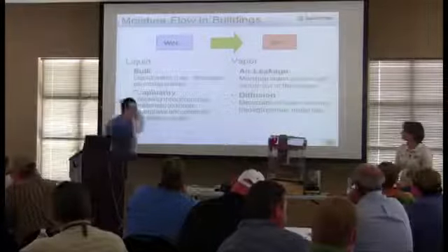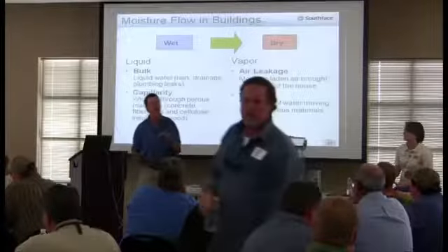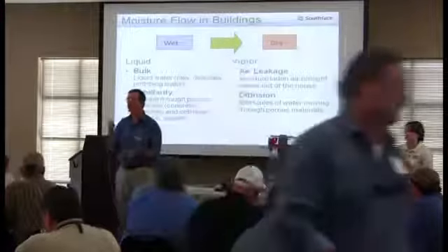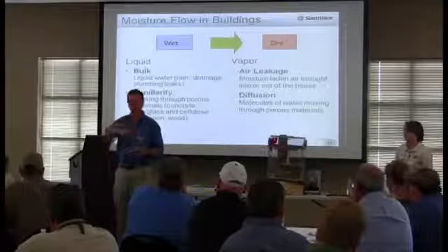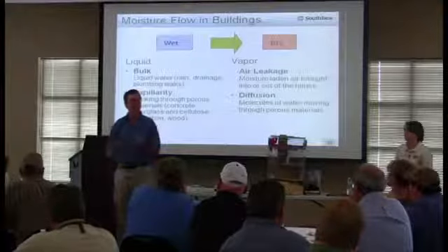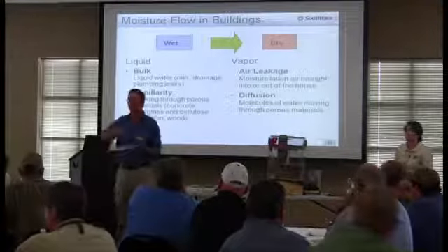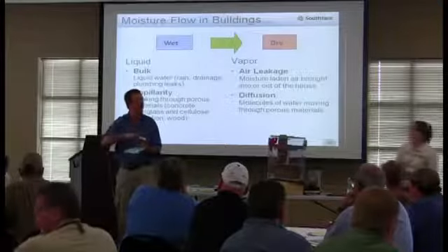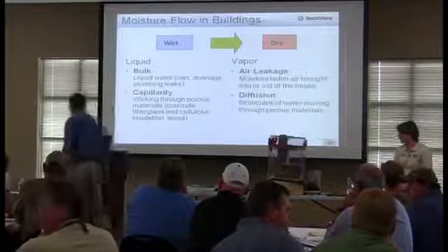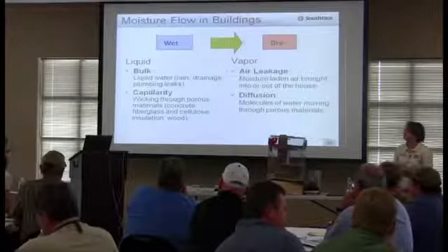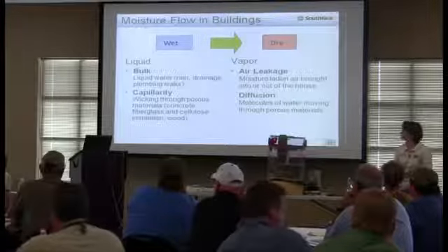And products like this seal gasket, when you have a slab and you transition from concrete to wood, we really like a product like this. In addition to running a bead of caulk on the edge, we probably want to put this as well. They make a 2x4, and this is a 2x6 version of it, because it provides air sealing and a capillary break, so it won't wick moisture up. So there are some little details like that that are easy if you do them during construction, but obviously hard to fix after the fact.